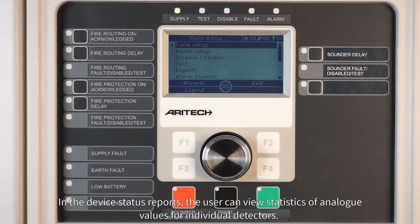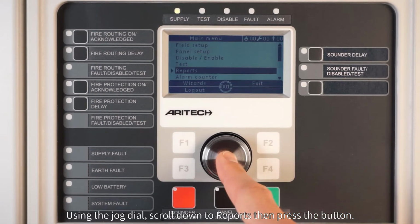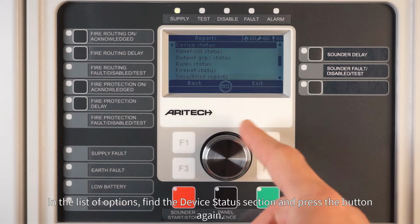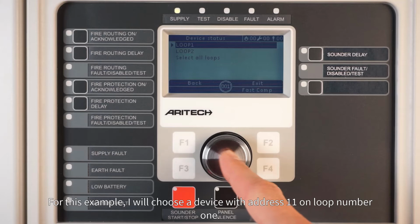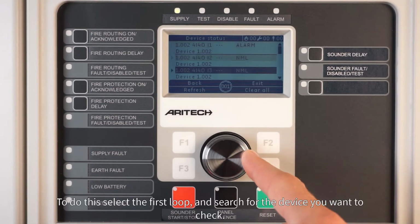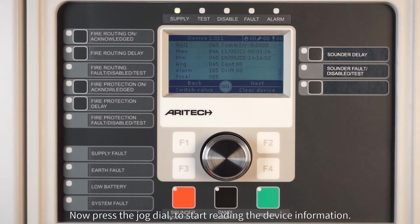In the device status reports, the user can view statistics of analog values for individual detectors. Using the jog dial, scroll down to reports, then press the button. In the list of options, find the device status section, and press the button again. For this example, I will choose a device with address 11 on loop number 1. To do this, select the first loop, and search for the device you want to check. Now press the jog dial to start reading the device information.